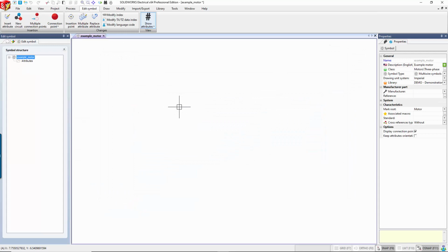Okay, so this tends to be one of the most confusing parts of the custom symbol creation. When you create this custom symbol, you're just left with this blank page, and you don't really have a sense of space. I think in some of the newer versions, it actually shows the origin in the lower left-hand corner, but in the older versions, specifically in 2019, it tends to just live a little bit off page and you can't really see it. So I'm going to just hold my middle mouse wheel to scooch this over so I can see my origin. So I'm just panning that over.